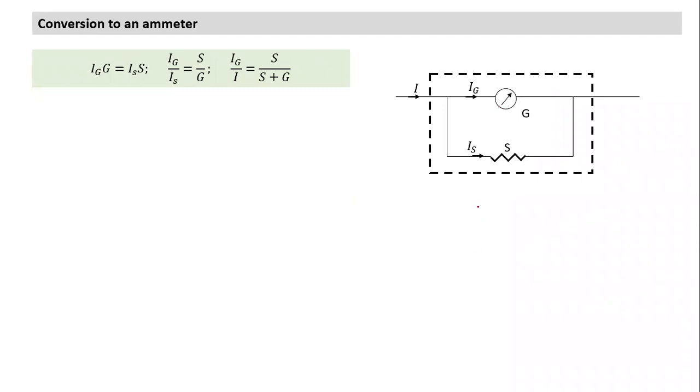Okay. So what is an ammeter? An ammeter is not only a galvanometer. This entire assembly shown within the dotted line is an ammeter. An ammeter is a galvanometer with a shunt connected in parallel. And this is the current coming in, which within this gets bifurcated. By measuring this, I can calculate this quantity. Okay, and this equation.